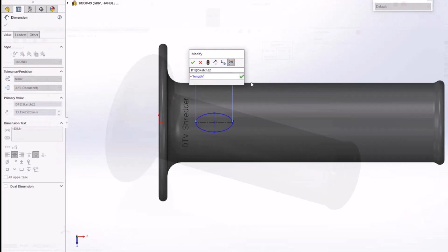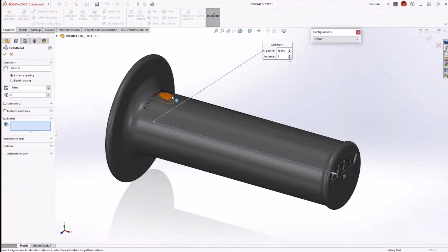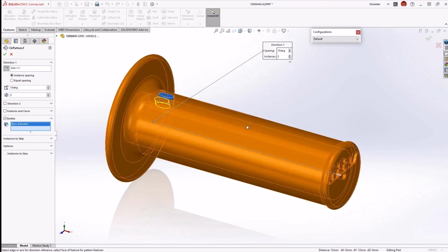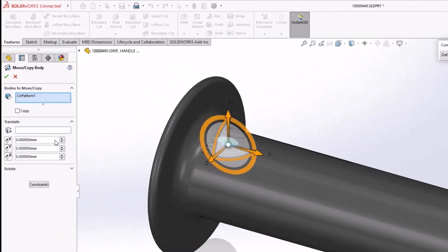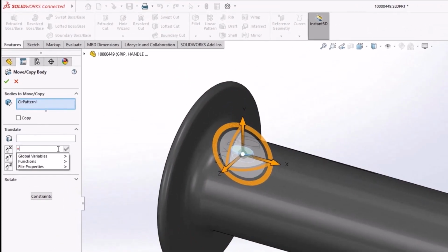and minor axes. Creating an offset body is easy in SOLIDWORKS, but how far along the handle should we place it? Since we're creating a pattern of these bodies, it would be best to define the parameter based on a global variable that also defines the spacing of the instances.